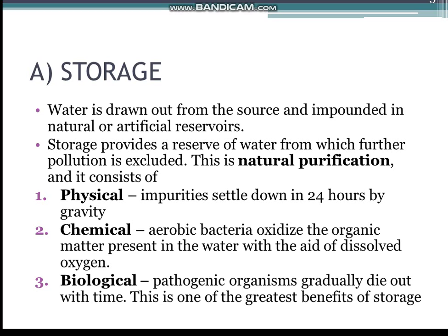Second, chemical. Certain chemical changes also take place during storage. The aerobic bacteria oxidize the organic matter present in the water with the aid of dissolved oxygen. Third, biological. A tremendous drop takes place in the bacterial count during storage. The pathogenic organisms gradually die out.